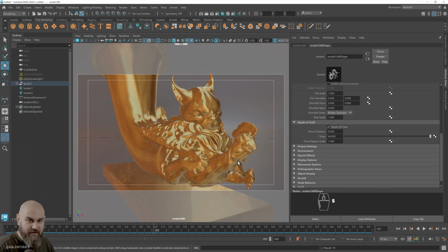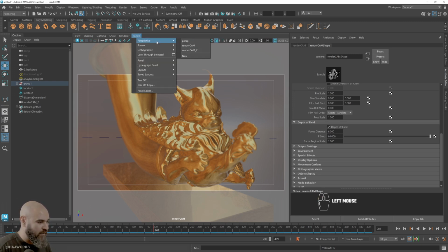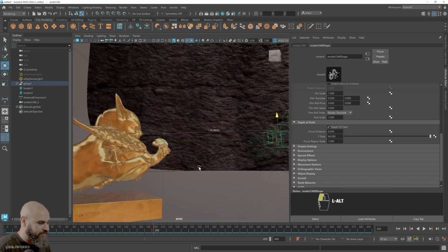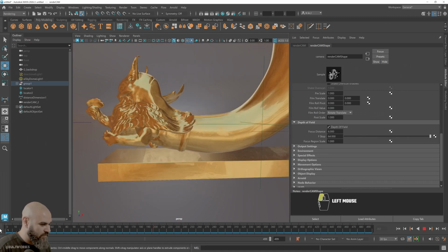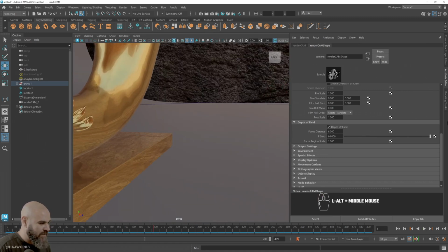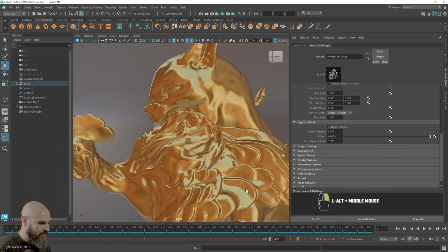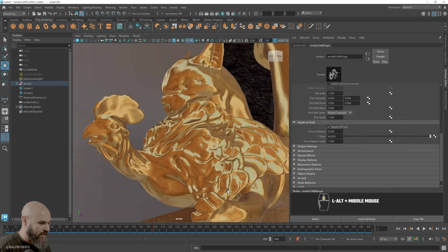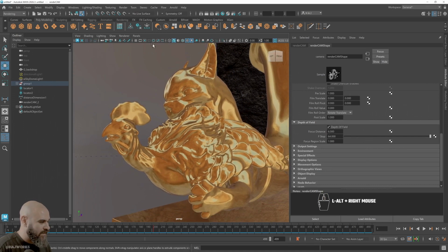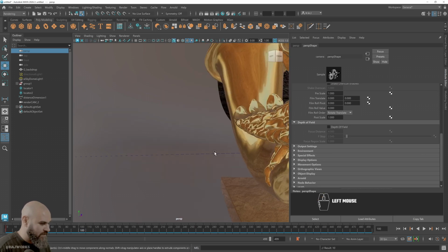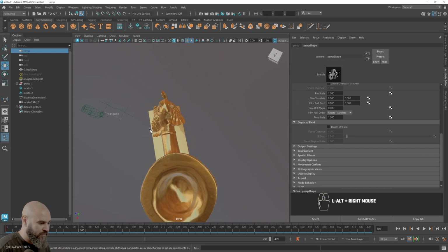What I actually like to do is, with the perspective cam, you could use it to also set different angles that you like, and set keys on the perspective cam. So like, you like this angle, you select camera, S, let's go to frame 100, at this angle, I kind of want to show from this angle.